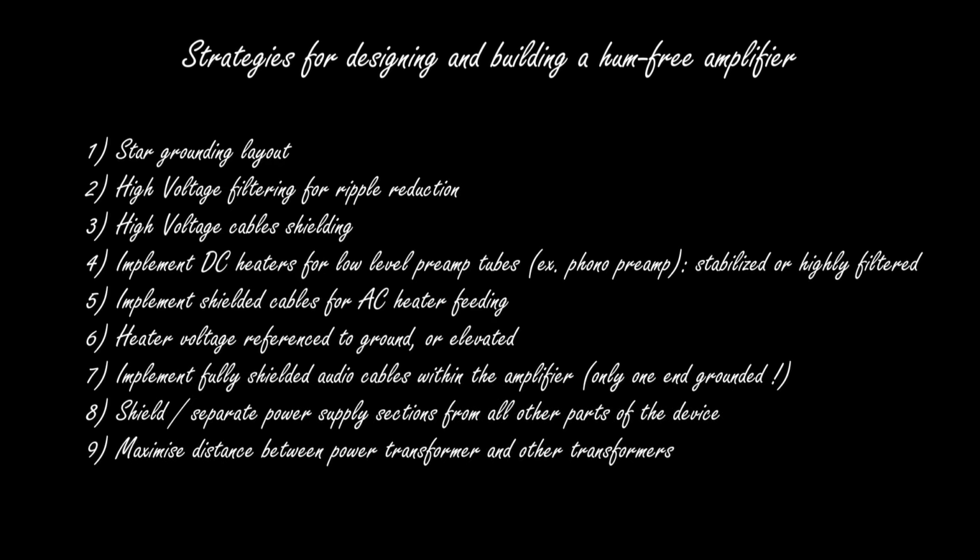Also, it's very important to try to maximize the distance between the power transformer and the smoothing impedance and the output transformer. This is because both the smoothing impedance and especially the output transformer can pick up the electromagnetic field radiated by the